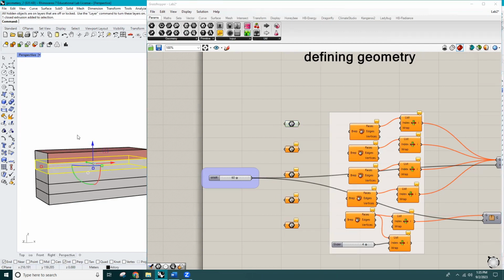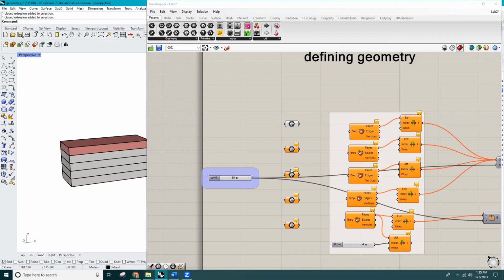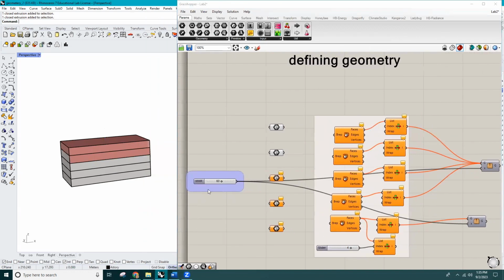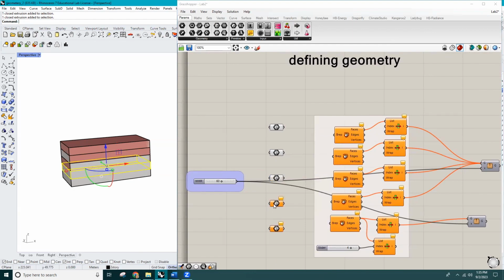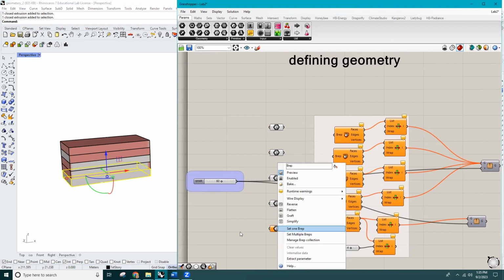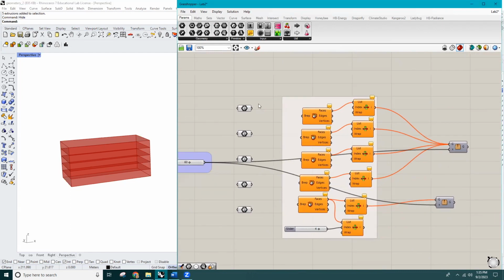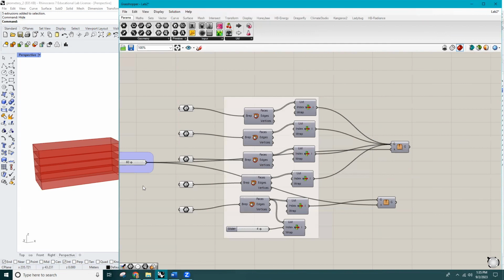Go to the params menu and drop a BREP component on Canvas and define each story of the building as their input. Then connect them to the explode BREP component. This part of the recipe is to select the surface of the exterior walls that you want to have windows.